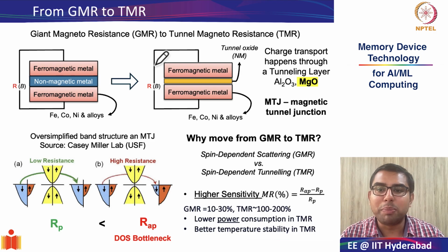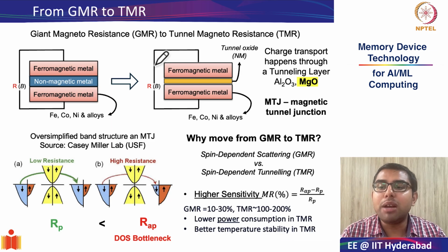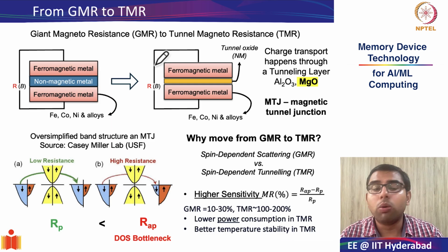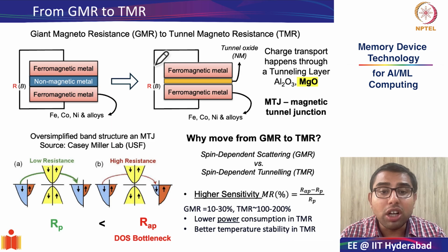So last time we began our study of magnetic RAMs or MRAMs. Let us do a brief recap of what we studied the last time around. First, we introduced the spin degree of freedom, and we saw how spin can be used to store and manipulate information, and that is done by breaking the so-called spin degeneracy through the application of magnetic fields. The key advantage of using spintronic devices was the promise of having low power operation. This is because spin currents are inherently dissipationless.